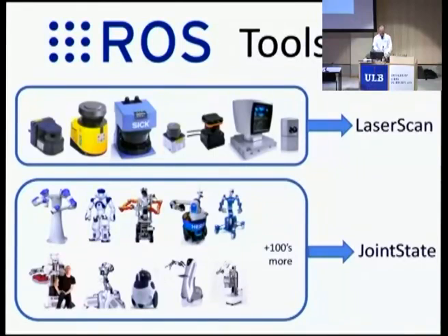There's a thing on the top that spins around, and then they output typically a custom binary message. So this is a picture of 7 laser rangefinders there. They all have their own custom binary protocol. The nice part, though, is that now everything has been bridged to ROS. So all these things output laser scan messages. So if you turn it on, start up ROS, start up the laser driver, you're going to have laser scan messages coming out, which is general enough to be able to define the output of all those scanners.